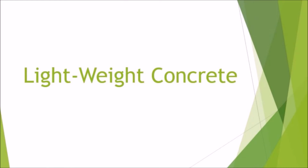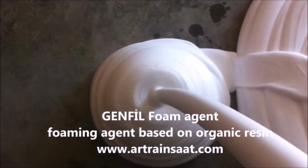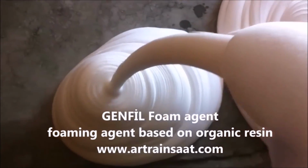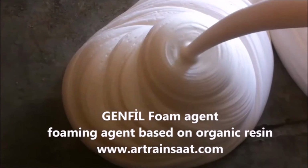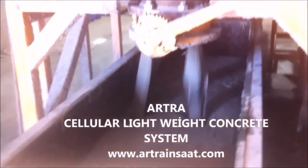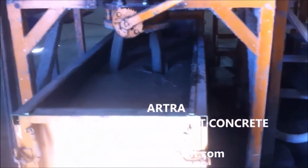Lightweight concrete, also called foam concrete, is a versatile material which consists primarily of a cement-based mortar mix with at least 20% of volume air. This air volume comes from a foaming agent that is mixed with the cement binder to form the concrete mix. The material is now being used in an ever-increasing number of applications, ranging from one-step house casting to low-density void fills. Generally, it has excellent thermal and sound insulating properties and a good fire rating.